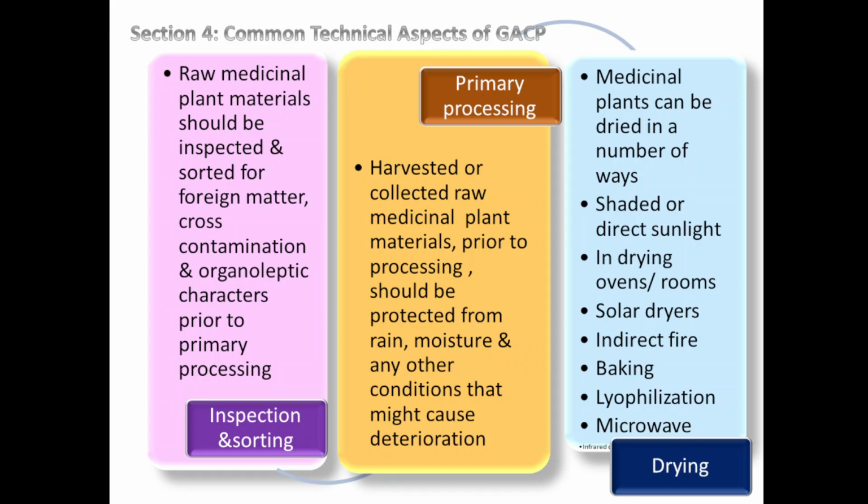The sun rays are spread over the glass and absorbed by that, and the air becomes hot, and the hot air is circulated over the material and the moisture is removed. That moisture or hot air is removed through the outlet. In this way it is heated in case of direct heating.